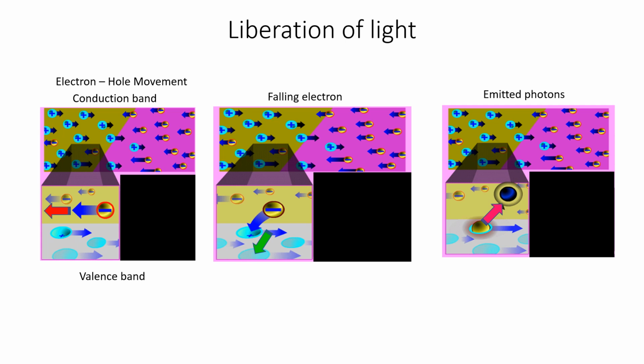The brightness of the emitted light is directly proportional to the forward bias current. So if we increase the forward current, we will get more and more photons. In normal silicon and germanium semiconductors, this entire radiation of electromagnetic wave during recombination is in the form of infrared radiation. That's why we cannot see the light in the case of a PN diode. The wavelength of the infrared is out of our visible range. Infrared electromagnetic radiation is nothing but heat that we can feel but we cannot see.